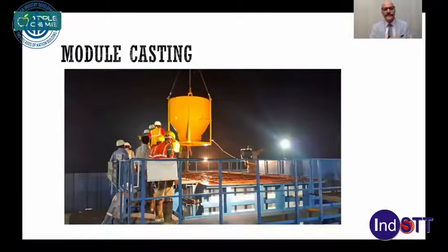Because what gives you a benefit is, if you look at the overall construction, friends, when you are doing a building construction, maximum time is spent in the service area, because in the toilets and washrooms you have got electricity, water, service lines, plumbing, hot water, cold water, so many things. But if you have got all the things already embedded in a service block, and the service block is made ready with the sanitary fittings and brought directly to the site, it saves a lot of time and it makes a lot of sense to do the work that way. So that is one plus point of precasting.